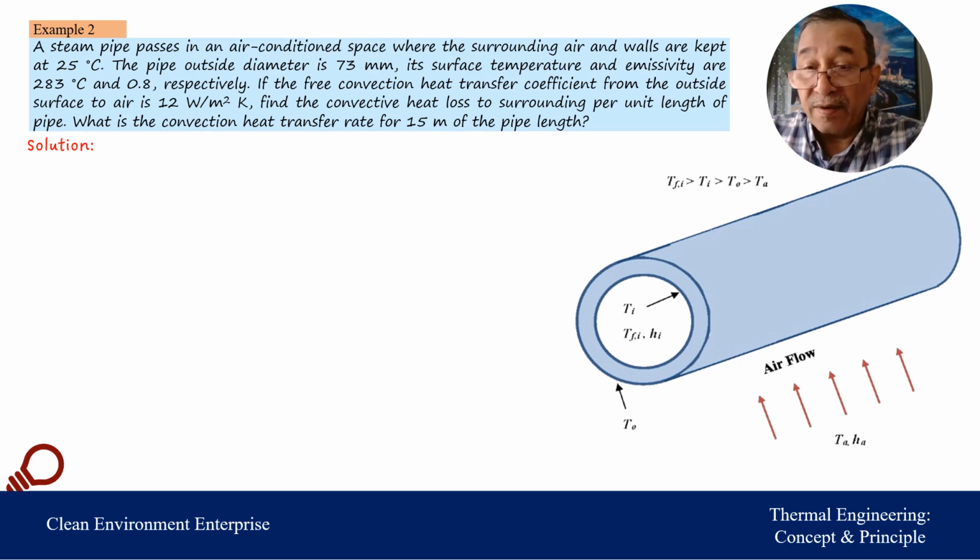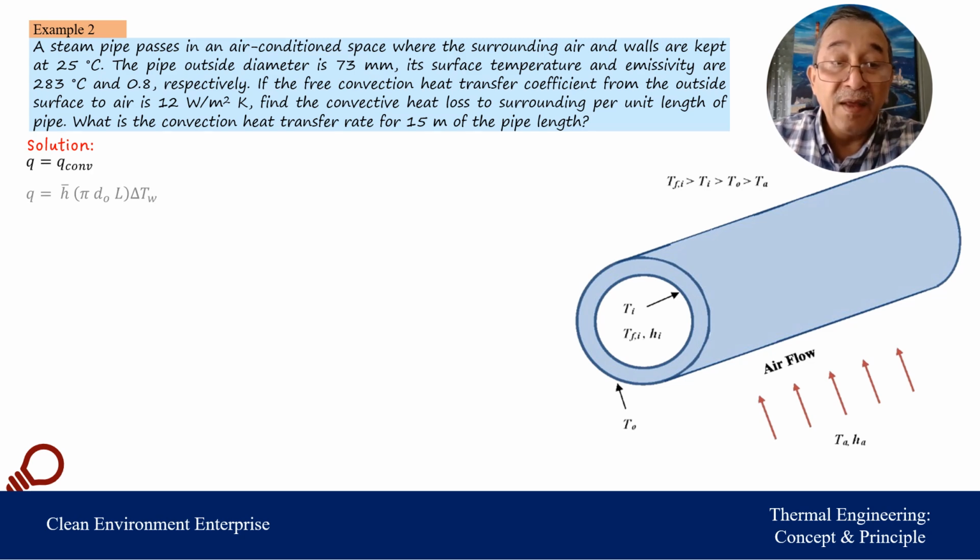We have here convection heat transfer on the internal side, and we have Ti, and Ti is greater than T ambient, therefore we expect the heat loss to go out. And if we take the convection part, Q equals h A delta T, and A here is pi D naught L, and that's why we are using the external heat transfer coefficient in this equation.